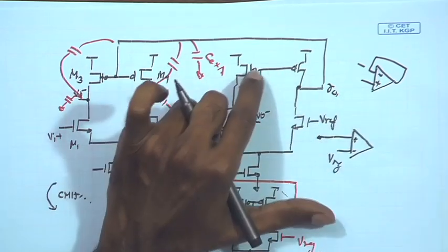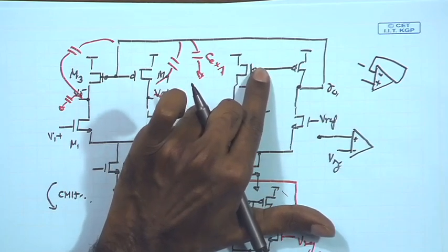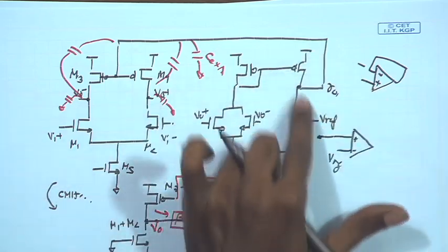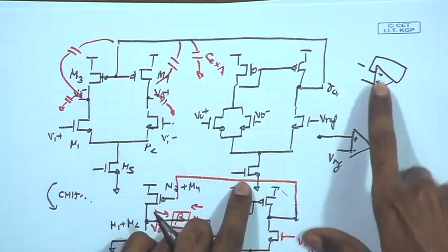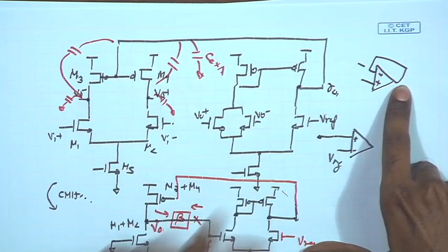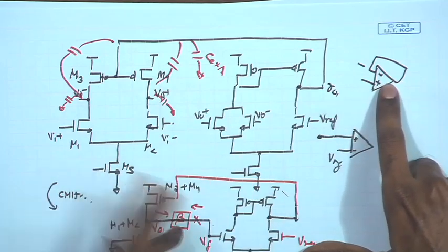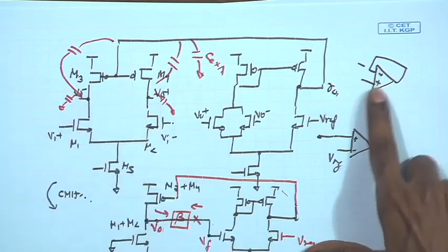It also has multiple poles, but these are at higher frequency. If you are looking at a direct connected load, this point will be at higher frequency. So you can construct a sufficiently good buffer just using a single stage, because when we are using these buffers, we don't want very precise unity gain. It should just be approximately able to follow. So we can use a single stage differential amplifier to produce a buffer.